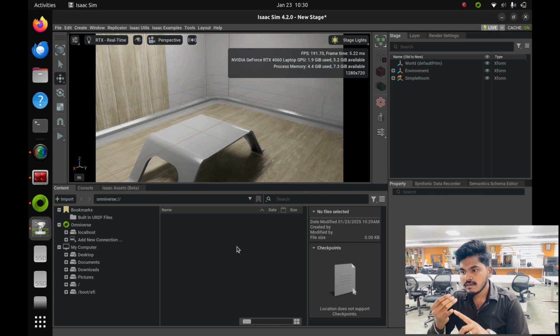The robot needs to know where it is, where am I. So for that we use the odom topic and the TF trees to give the position and orientation with respect to the map. Then we need a command velocity to drive the robot, and the 4th topic is the scan topic. Through the scan topic the robot gets information about the environment.